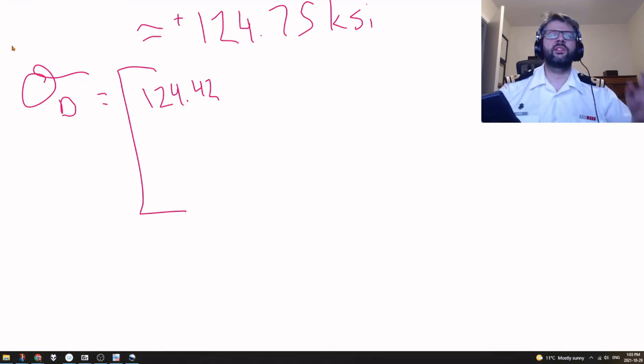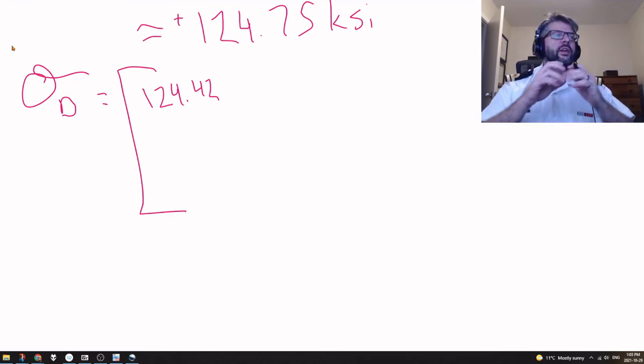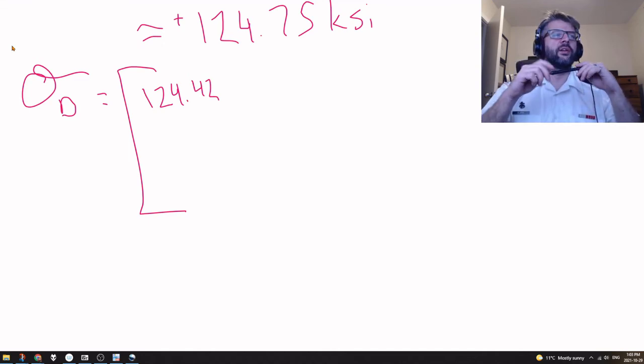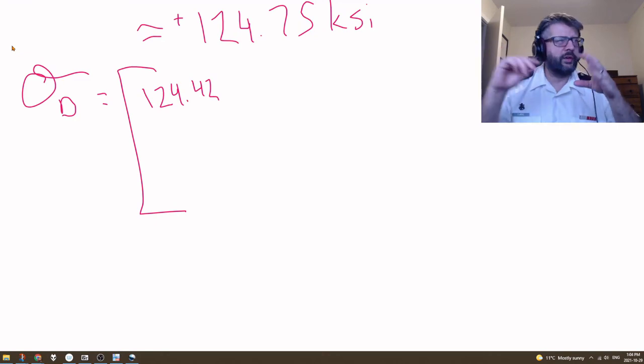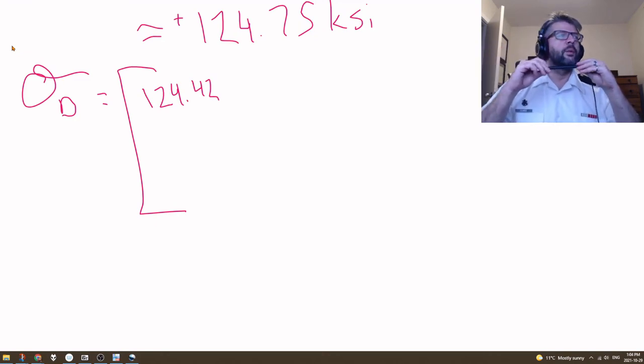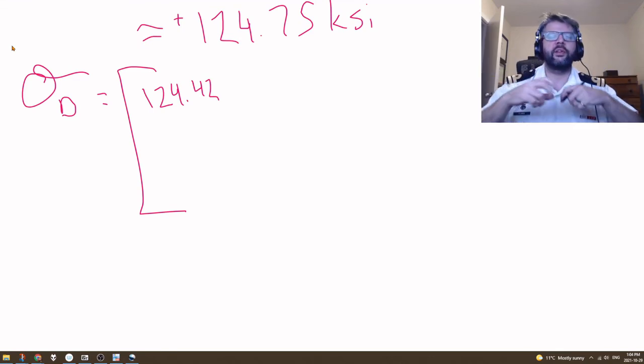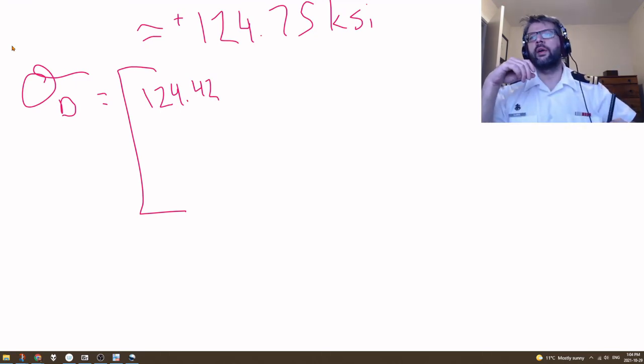And again, the x direction is the only one that's going to have any normal force on it. There's nothing squeezing the tube from either side. It's not getting thinner like that. There's no force causing it to get thinner. It will be getting thinner due to Poisson's ratio, but we're not calculating that, so let's not worry about this. It also doesn't have any hoop stress, either positive or negative. Nothing's trying to stretch it out like that. So our y direction is 0, and our z direction is 0.